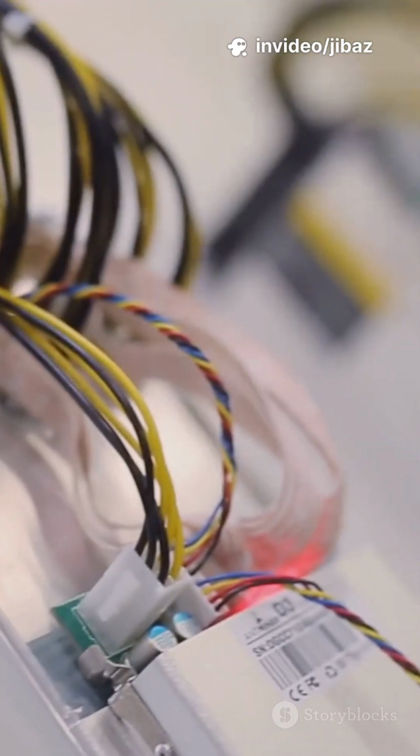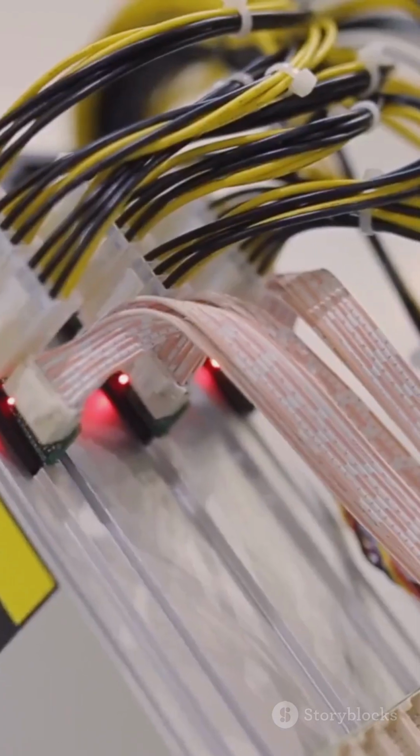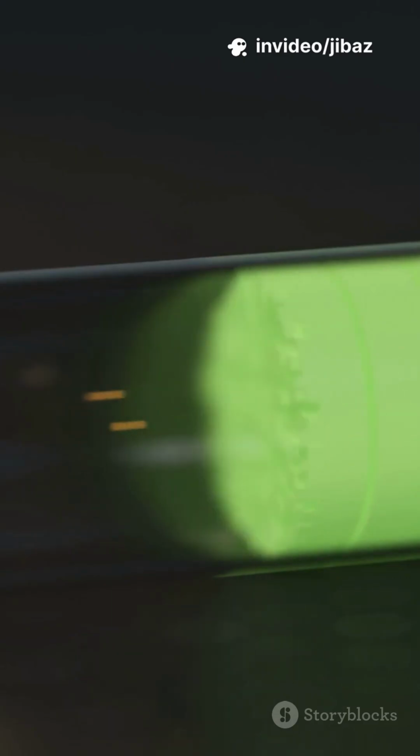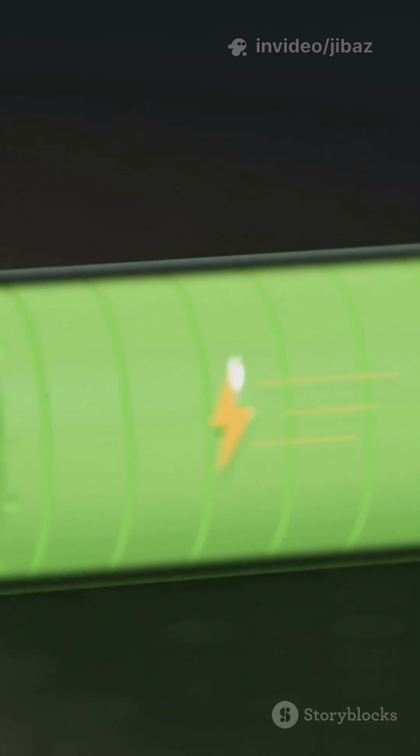For higher efficiency, modern systems use switch-mode power supplies, SMPS. Instead of burning off excess voltage as heat, they rapidly switch the input using transistors and store energy in inductors or transformers. These converters can step up, step down, or even invert voltages with efficiencies over 90%. That's why they're used in computers, chargers, and amplifiers.